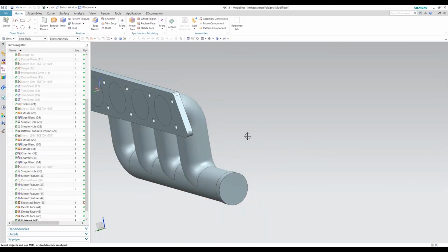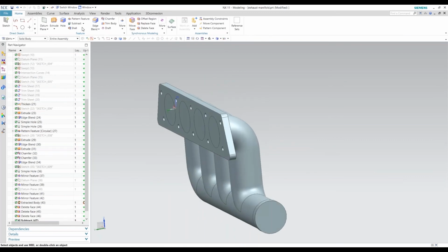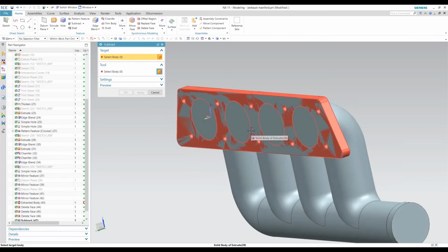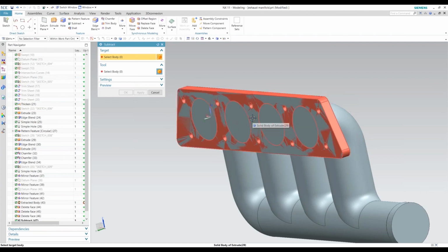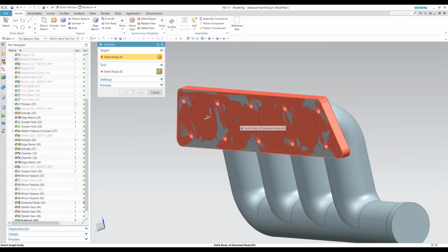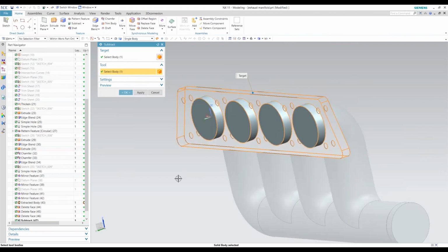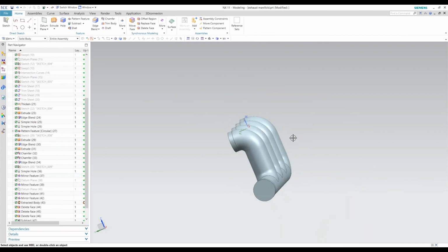Now we have the inner volumes here. I'll do the same thing on this one here. I'll do subtract. It's kind of hard to grab the correct one. You can kind of see which one you're grabbing based on the circles or based on the feature name. So this one's 43, this one's 29. Okay, so I'll delete that one from this. Okay. And so now, again, I have the inner volume.